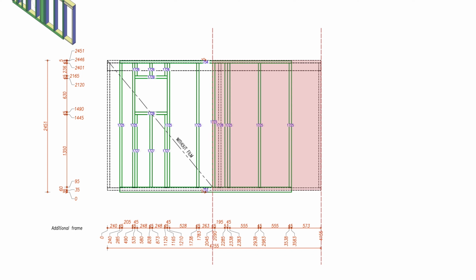The reason is this: as this is a wet room wall element, at a later stage an additional barrier is applied, and as two vapor-tight barriers are not allowed in construction, it might cause moisture issues. Then only one solution is chosen.